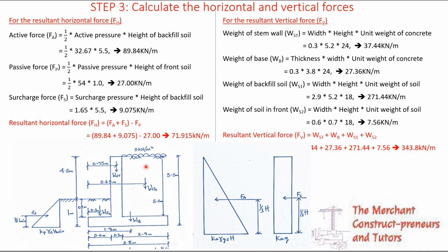Now the soil is exerting two forces, horizontal force and vertical force, and that vertical is the weight of the soil on the base, on the heel side, on the toe side, still on the base, right? Then for the horizontal pressure, you can see that one is acting on the stem, that of the soil on the heel.